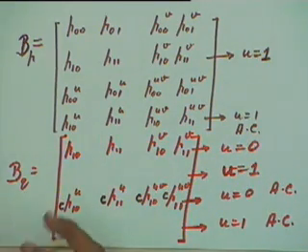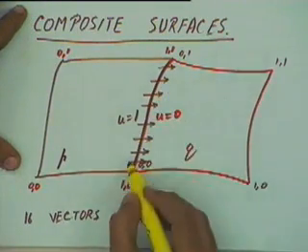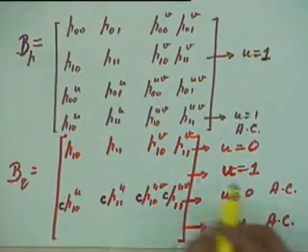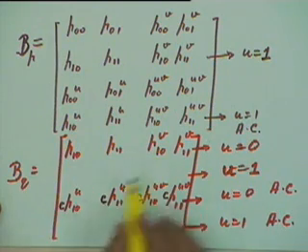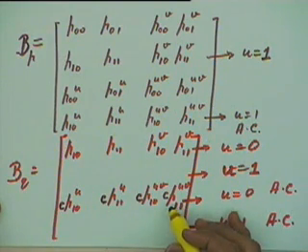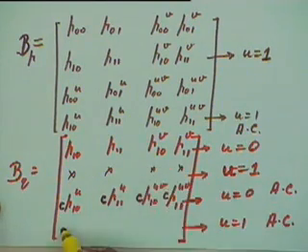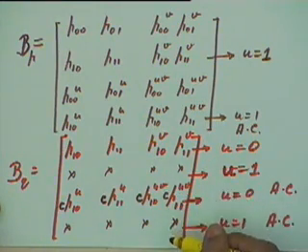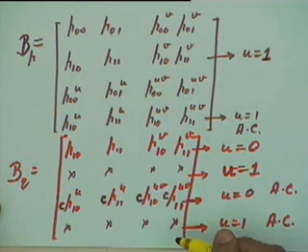Only then the tangent vectors along this edge will be in the same direction. The magnitudes can be different. So for the input matrix for the Q patch, out of the 16 terms, 8 terms will get fixed like this and the remaining 8 terms can be anything. Whatever the remaining 8 terms be, the 2 patches will always have a C1 continuity at the common edge.